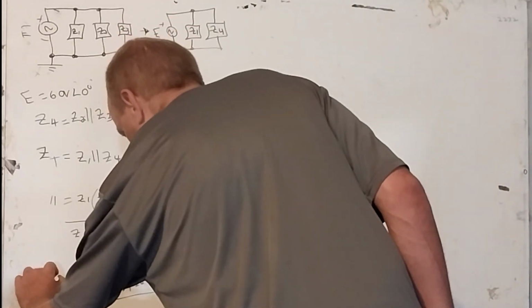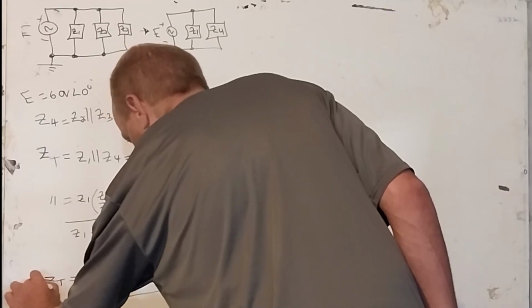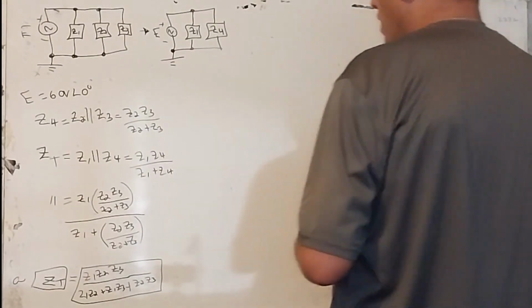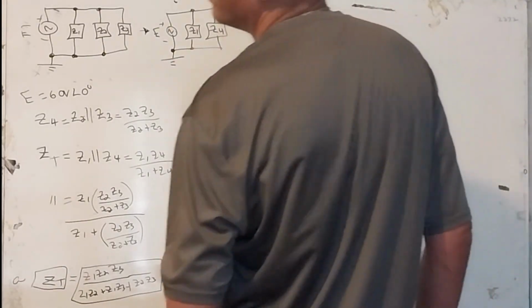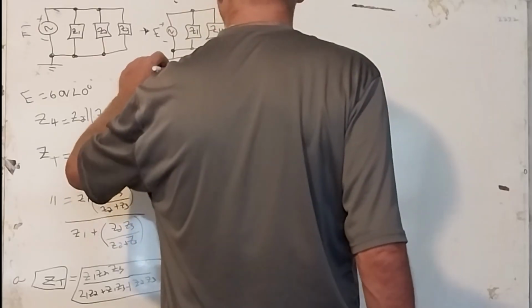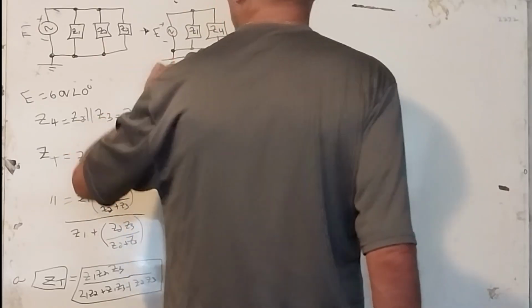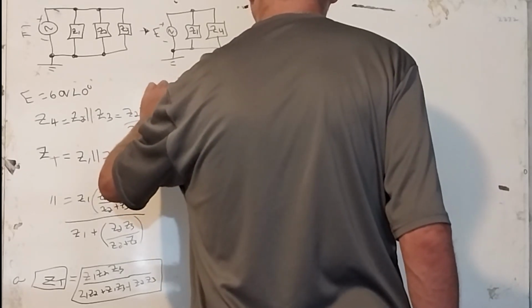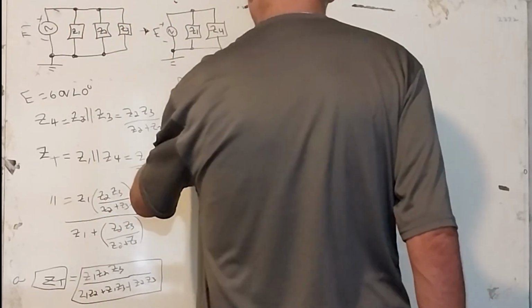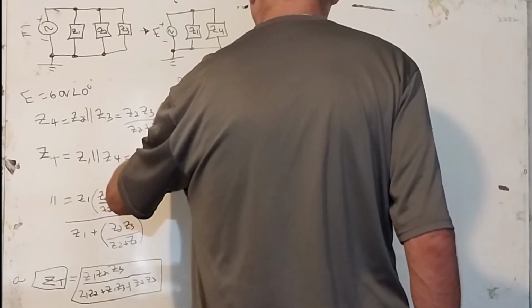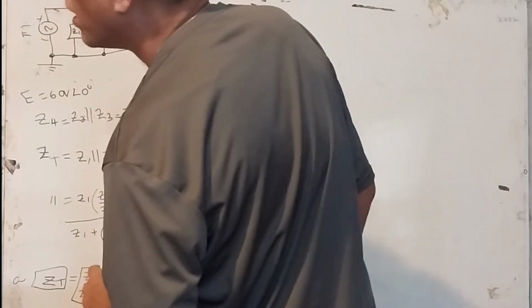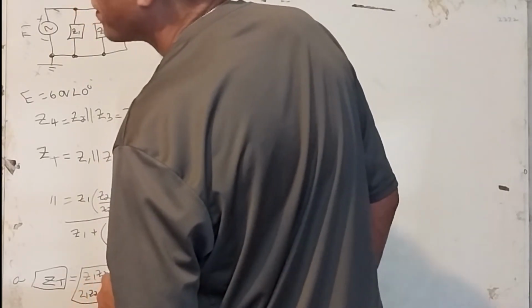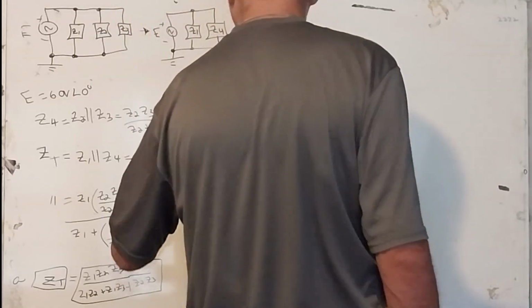Now, it's probably good to write that here since I got that. All right, here's our first problem, Z sub t. So let's get these values. R1, let's see, R1 is 2 ohms. R2 is 3 ohms. X of L, 6 ohms. We have 2 capacitors. X of C1 is 9. X of C2 is 2.